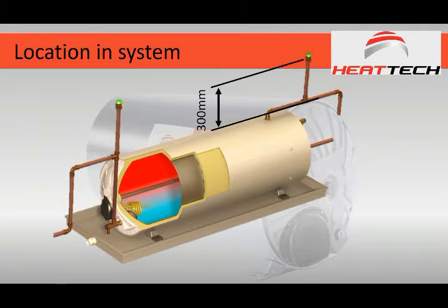So when you do a 400 kPa installation, all the components must be 400 kPa. As far as I recall, it is only the geyser that is then allowed to be of a higher pressure rating and not a lower pressure rating. And similarly, if you do a 600 kPa installation, all the components must be 600 kPa. And the same obviously applies for the lower pressures, which is not very common.